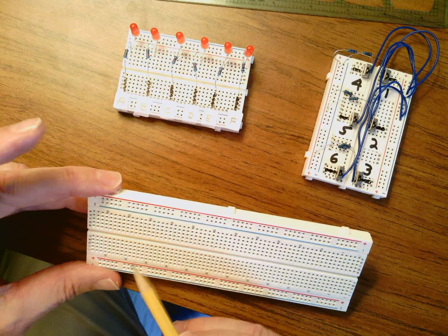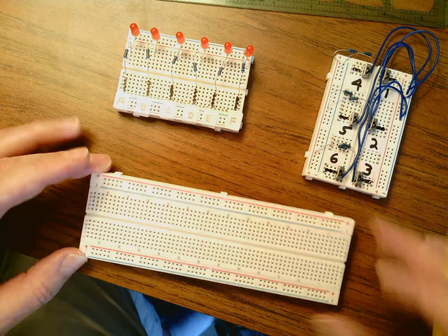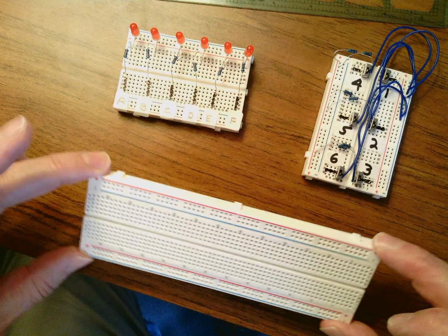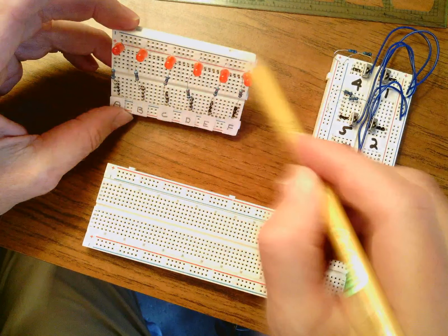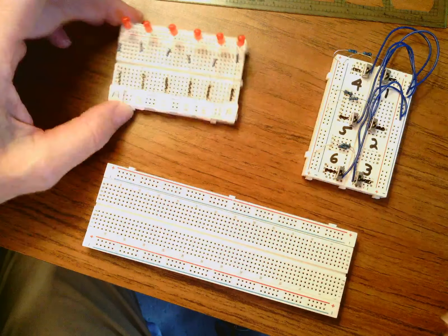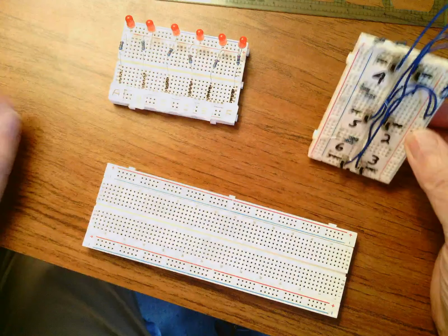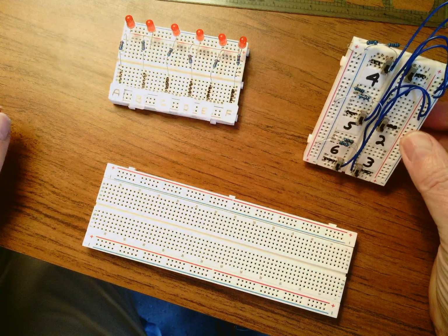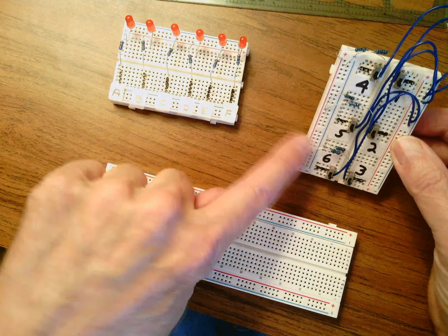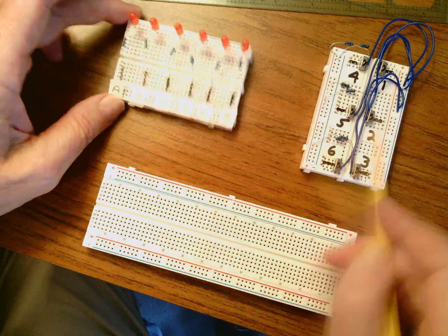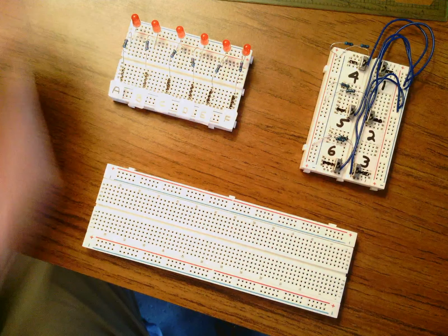Your 5 volts will always be on the outside red, and your 0 volts, which is ground, will always be on the bottom blue. So, laying out the boards, the red rail on the large board goes at the top. The blue rail on your LED assembly goes at the top. And when you lay out your data switch board, I want to make sure that it's positioned vertically, and you'll see why as we go through the labs, and this red rail is to the left. So make sure that you lay those out that way at the beginning of every lab.